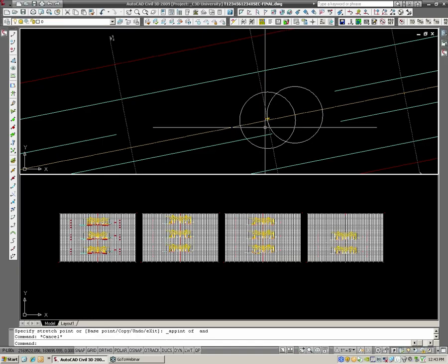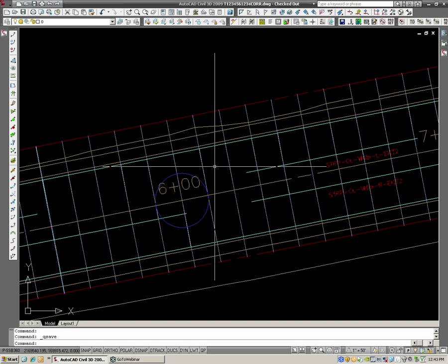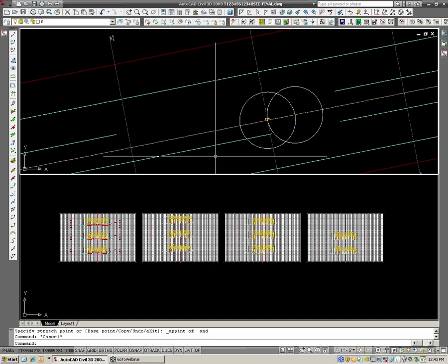I could pull my corridor model and have the corridor frequency set to every foot. So this corridor model would be very accurate, sampling every foot. But I could still only just pull my cross sections every 50 feet. Does that make any sense?